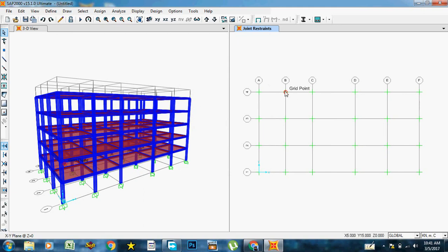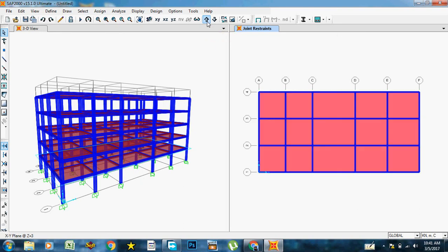So this is our ground floor, or this basement, or say foundation floor, and we should go to the top. For this, click here in this window and click here. This is move up in list, it is written here. Move up, we go one floor up, second floor, third, fourth, up to the top floor. We are at the top floor now. We are going to place our stair somewhere here, anywhere we want. I'll put it here. So for this I need to make a roof cover.